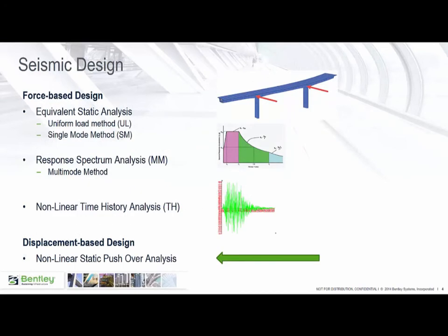Seismic design. There are two commonly used seismic design methods: force-based design and displacement-based design. For example, the AASHTO LRFD bridge design specifications address the force-based design, whereas the AASHTO guide specification for LRFD seismic bridge design covers the displacement-based design.